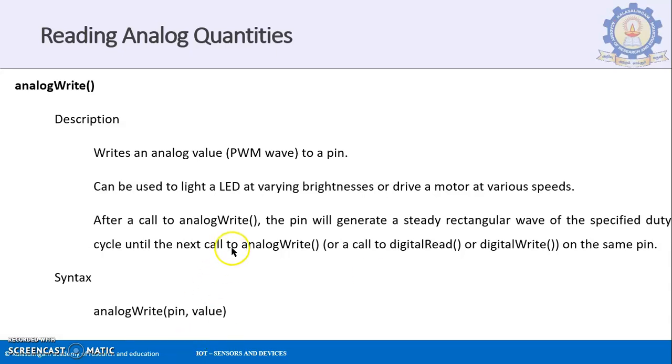After a call to analogWrite, the pin will generate a steady rectangular wave of the specified duty cycle. The on time and off time form a particular cycle, and the on time of that cycle is what I call the duty cycle. This continues until the next call to analogWrite, or a call to digitalRead or digitalWrite on the same pin. So please remember, the rectangular wave is generated when you call analogWrite, and that rectangular wave has a duty cycle.